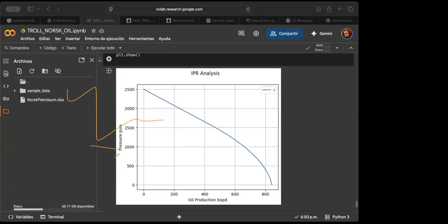And also when they are restarting the production, this affects the reservoir, because it's like when you are doing oil well testing. The pressure inside the reservoir when you close the well is affected, because it's a wave of propagation of drop of pressure or increase of pressure. In this case, the pressure increases inside the wellbore. When the compression reaches its maximum, there is an increase of pressure because the oil is not flowing from the reservoir to the wellbore. So when you are opening the wellbores again, the production has some differences. So you need to understand the data.